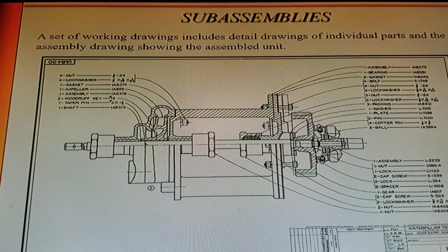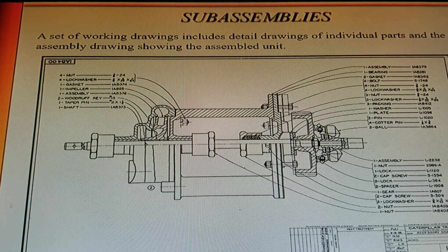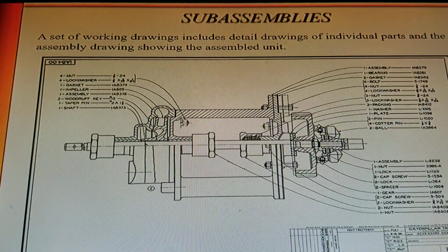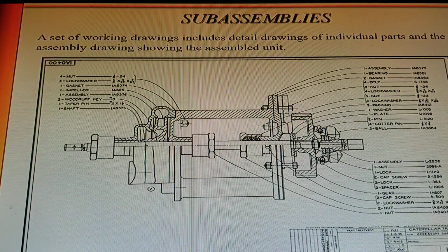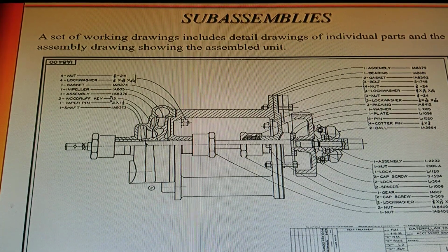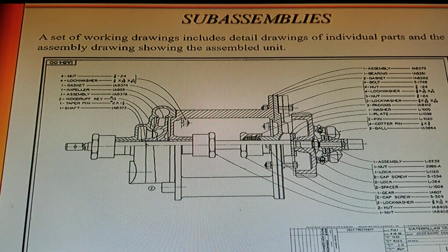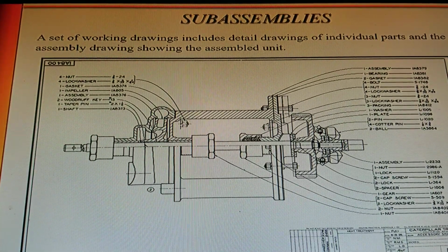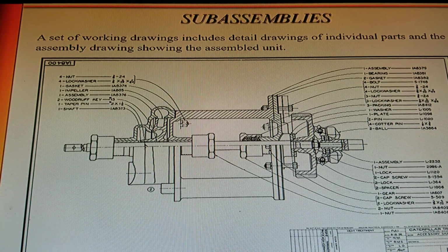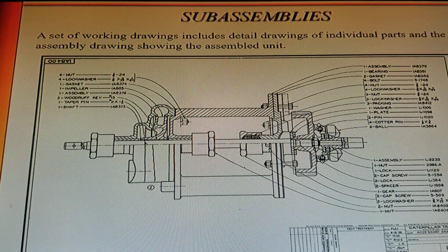drawing. And instead of having a parts list or a BOM, bill of material, you have arrows. Instead of balloons, you have arrows pointing to the description of each part. For example, in that top left one, it says a nut. It's what it looks like, a 3/8-24, probably a fine thread nut. And it has an arrow pointing down to what appears to be a nut on the inside of that section view.